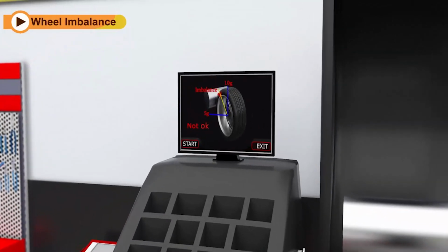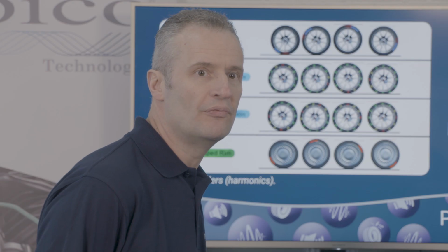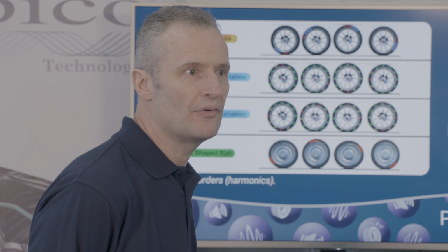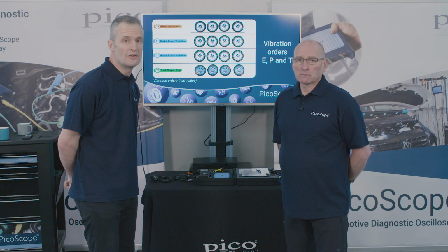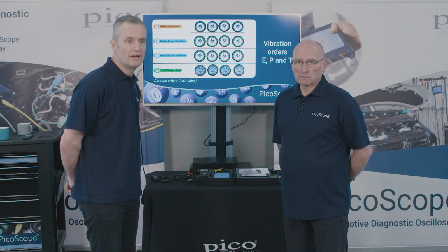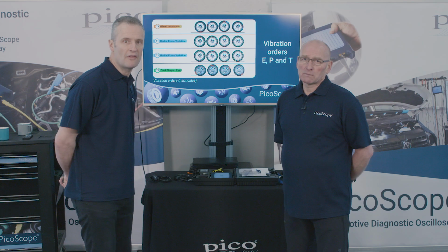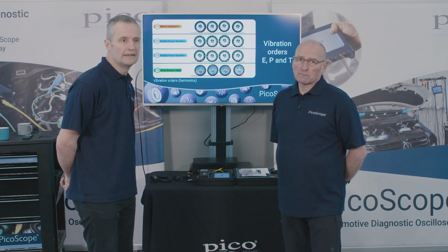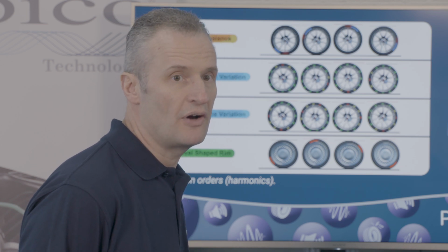The more high performance, the more rigid the chassis, the more sensitive suspension components become, the more radial force variation is visible and becomes a real issue. And without that style of wheel balancing, it's a real struggle to eliminate first, second, third order tyre vibrations. A certain must consider for low profile tyres.